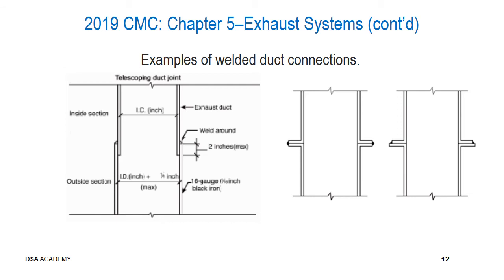characteristic to take from this particular image is the fact that the ductwork itself in this configuration is going to guarantee that the grease that's trapped inside of the ductwork remains in the ductwork, and the grease is actually going to shingle off of the upper piece of ductwork onto the lower piece of ductwork, and there'll never be a situation where the lap itself is going to contain grease.